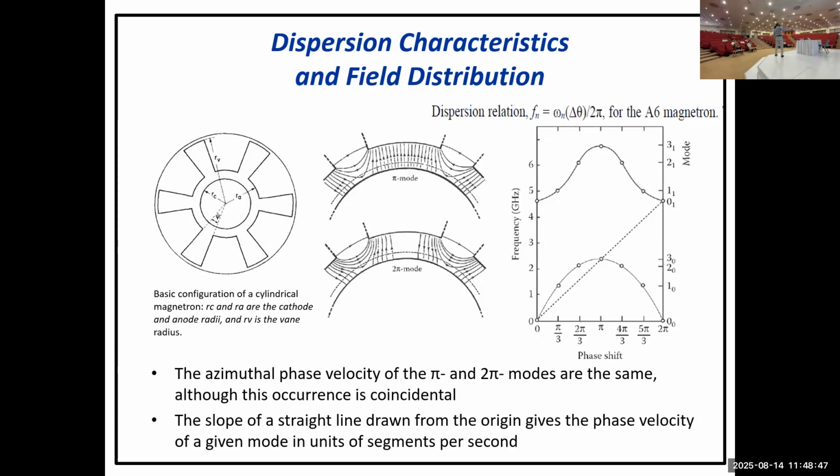But once you have an electron beam, I will show that the dispersion curve will be distorted, will be changed, because you're going to add instabilities. And this is how we extract RF from the electron beam. At the beginning, for the first couple of nanoseconds, the electrons are going at a uniform velocity, so there is no modulation actually, right? And then after a couple of nanoseconds, you start having some modulation, bunching, and you saw the spokes this morning, right? Spokes depend on the mode. The number of spokes here is different than the number of spokes here.